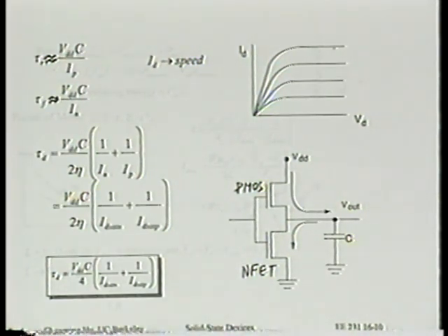Once you have done that, now you can ask, what's going on here? Why should we not divide this by close to 1, but rather close to 2? Well, it's hard to say exactly why it's exactly 2. But we can appreciate, I believe, that the rise time does not require this capacitor to charge all the way from 0 to VDD, right?